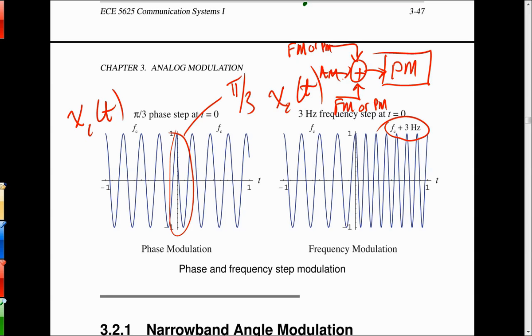So does that preserve signal integrity better than just single modulation? Not really. But it gives options. I mean, the subcarrier idea gives the option that the one signal contains everything, and when you demodulate it, you can choose to ignore certain things. Like in FM stereo, if you don't want to receive the signal as stereo, you can just focus on the monaural part, which has the left and right channels added together, and you ignore the left minus right, which is sent on a subcarrier. So you can play games like that, and that is backwards compatibility.